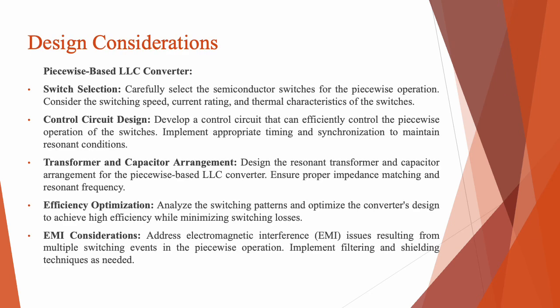Now the design considerations for the piecewise based LLC converter. There are a few points that I'm going to discuss. Number one is switch selection. Carefully select the switch semiconductor for the piecewise operation. Consider the switching speed, rating, and thermal characteristics of the switches.